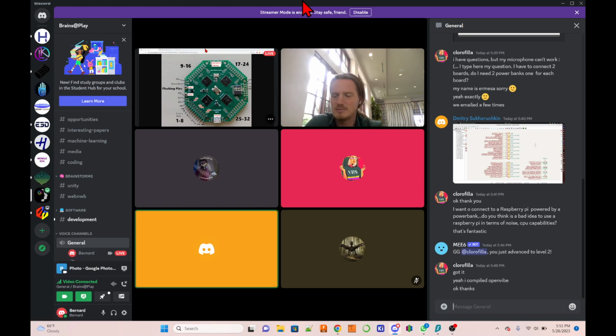So it depends on your appetite for noise. If your algorithm can filter this noise, then okay. I was testing some algorithm connecting just to a PC with the AC line enabled. So I have all the AC line noise, but it's filtered with a notch filter, and it's okay.